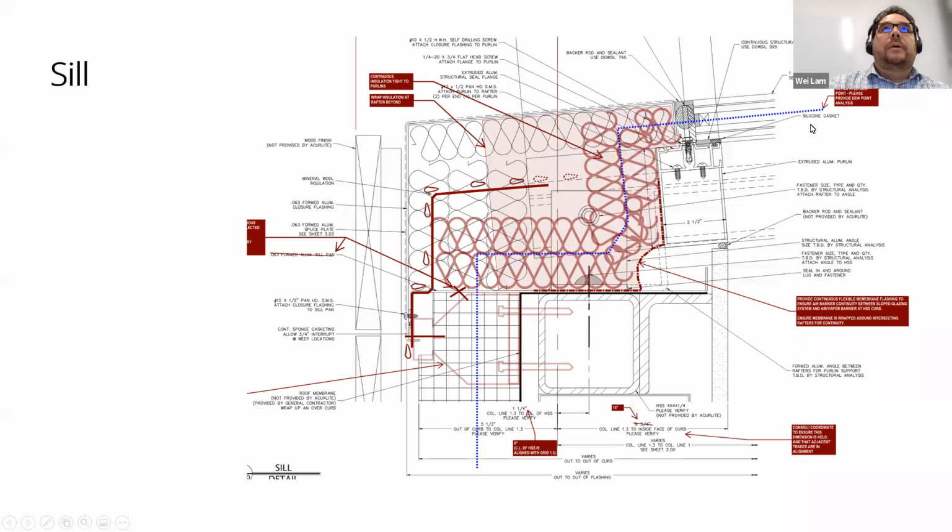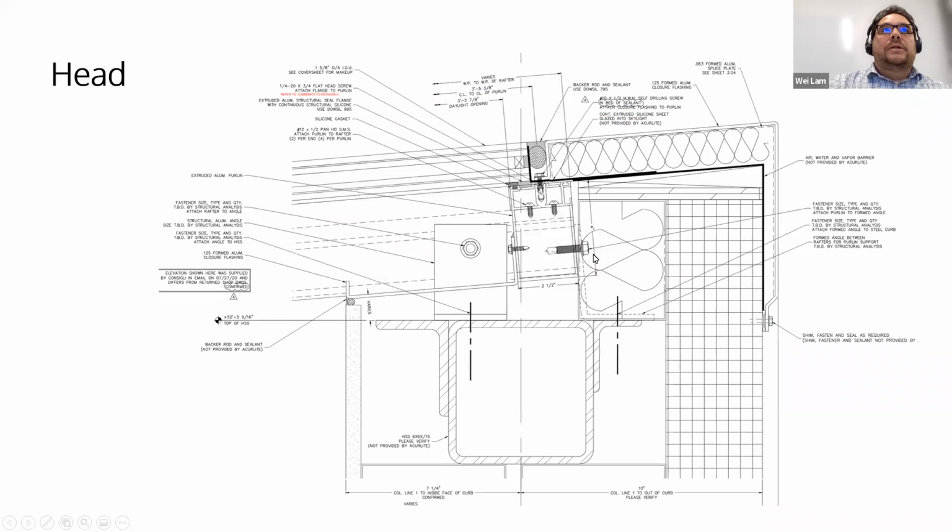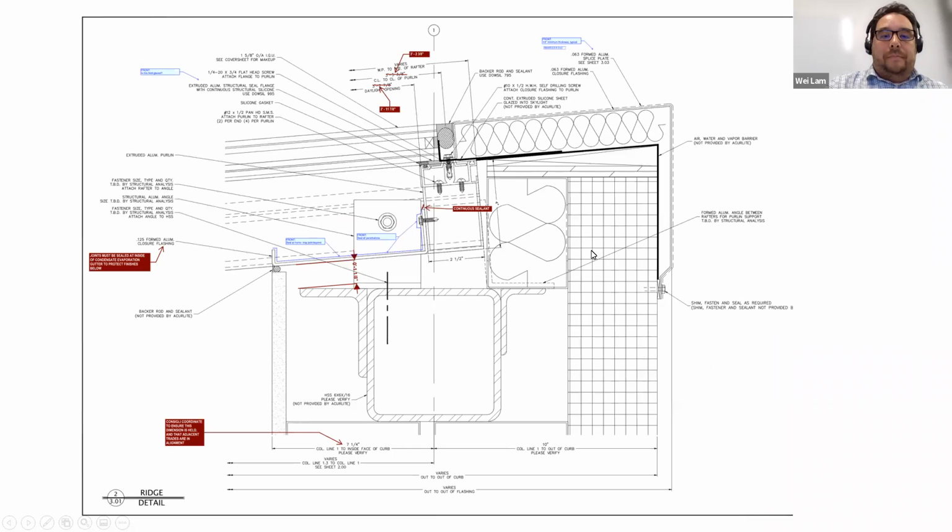And then this note up here, this was a question about dew point, but the condensation is going to occur on any of these surfaces, right? I mean, it's not going to occur within the insulation. These are non-permeable materials. We don't care if condensation occurs necessarily out in this zone, so long as it's managed. Similarly, enlarged section detail of the head.